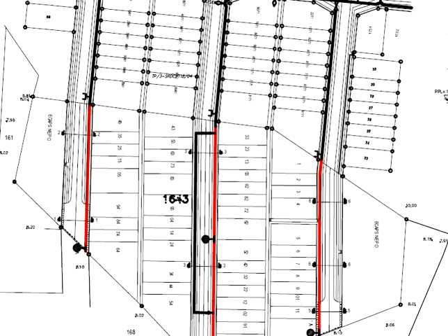These switch valves need to be strategically placed so that you can compartmentalize the service areas. In the case that there are requirements for maintenance, a minimum number of buildings will have the water supply disrupted.